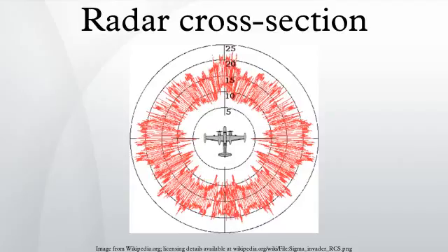This is a complex statement that can be understood by examining the monostatic radar equation one term at a time. Where P_t equals power transmitted by the radar, G_t equals gain of the radar transmit antenna, R equals distance from the radar to the target, sigma equals radar cross-section of the target, A_eff equals effective area of the radar receiving antenna, P_r equals power received back from the target by the radar.